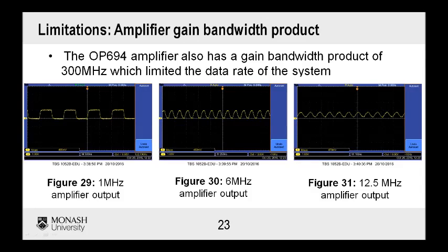The thing is that the gain of the amplifier means that the maximum frequency of the amplifier without exceeding the gain bandwidth product is approximately 11 MHz. You would think that this would have no effect on a 6 MHz signal, however you can see that the shape of the graph has changed. This is because a square wave will have harmonics, which have frequencies greater than 11 MHz which have been removed by the amplifier.